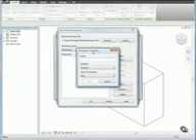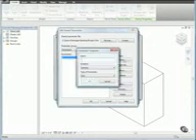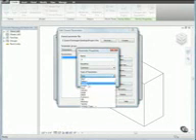And in the Parameter Properties dialog, for Name, type B. And under Type of Parameter, select Length and click OK. Then, under Parameters, click New again and type H for Name and select Length for Type and click OK.